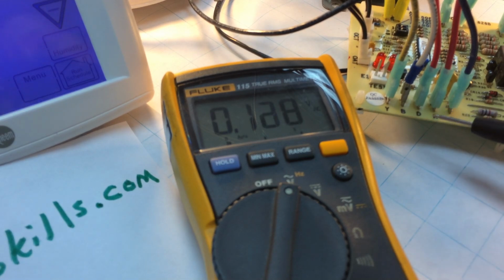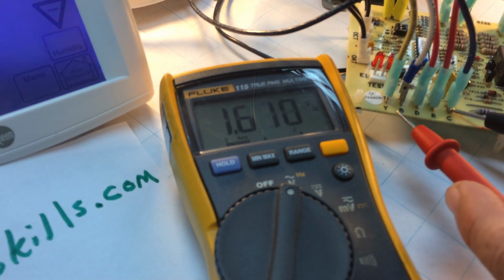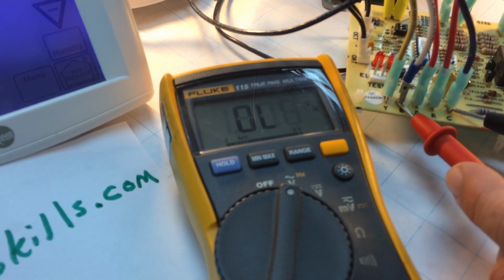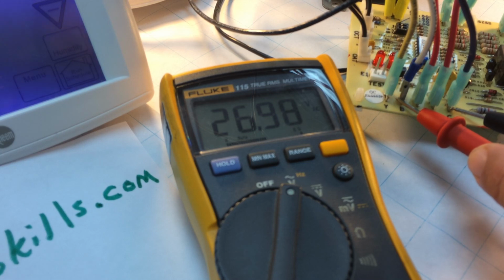So on an active call, whenever we want to establish if the thermostat is calling, we're going to use one meter lead and always reference our common, and then we're going to see what is calling on the other terminals. For instance, on this heat pump, common and B is energized because this particular unit energizes the reversing valve in the heating mode.